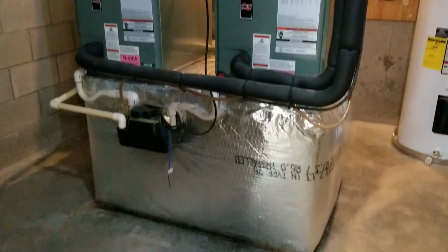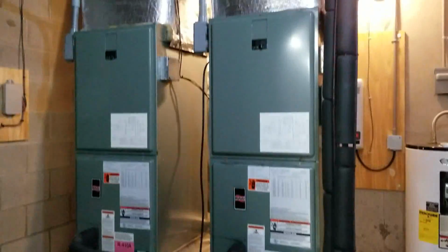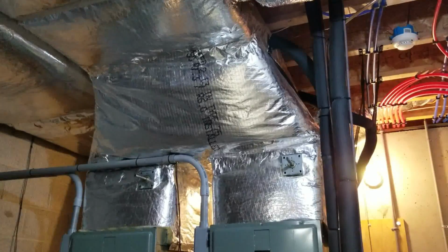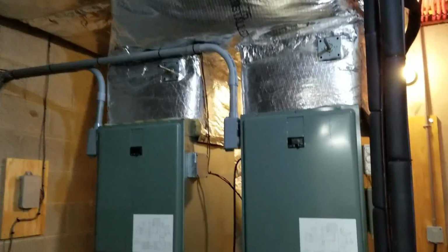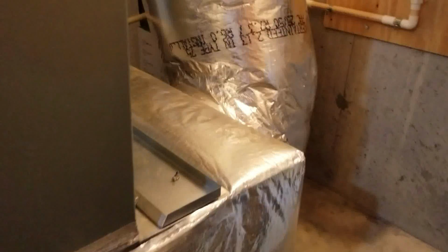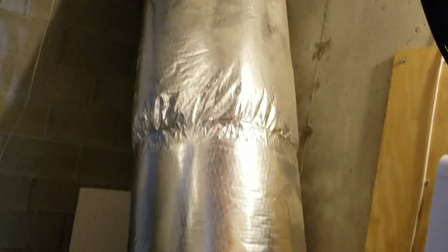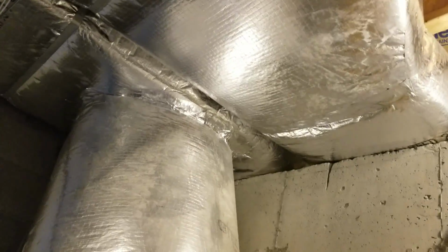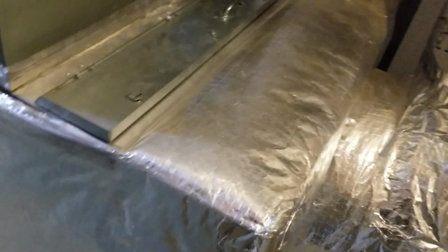I showed you earlier. There's that return air box on the bottom. Of course, it's all insulated. And then up here at the top, you can see the duct combining box up there. Let's go around to the back side, and you can see the return air. So if you recall on the video of the CAD, is a 24-inch diameter return air duct that goes up to the return air trunk. So that's the return air trunk there, and the supply trunk right next to it comes down here and goes into the return air box.